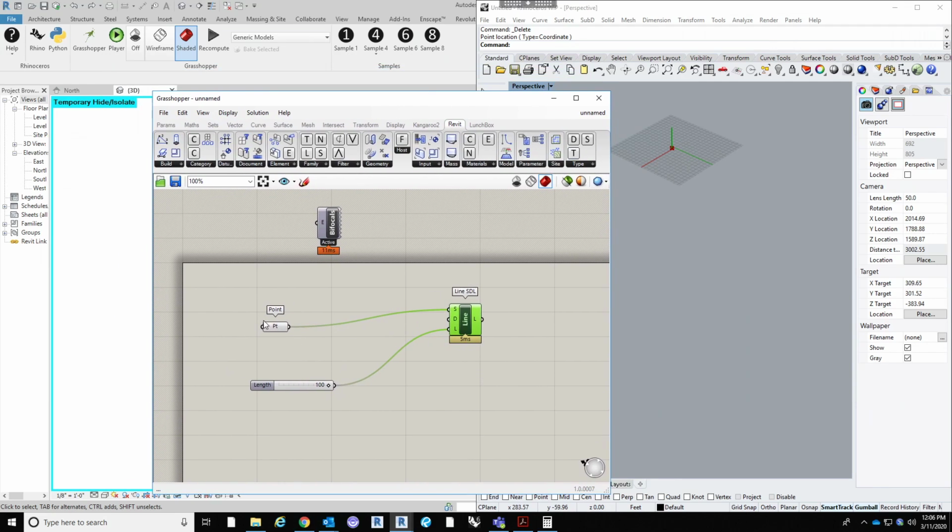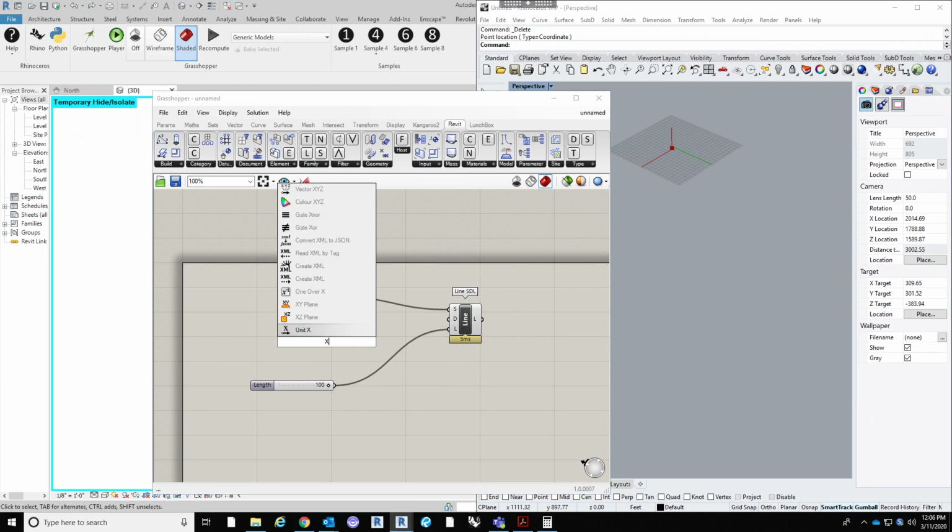And we'll be creating a wall from this line. One thing to remember with wall geometry, and in a lot of the geometry that we'll be creating in Revit, it relies on horizontal members. So the lines that you create must be fully horizontal. They can't be undulating in the Z direction. So let's change this to the x-axis.